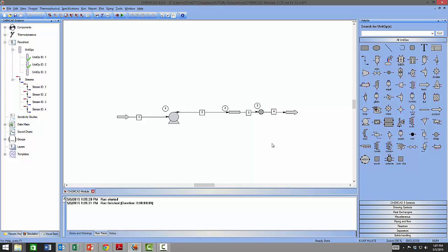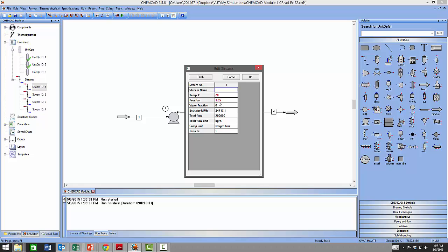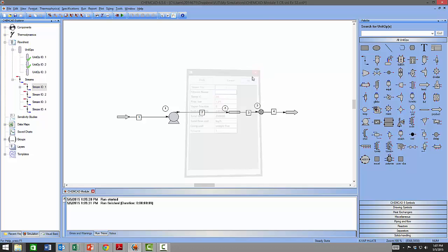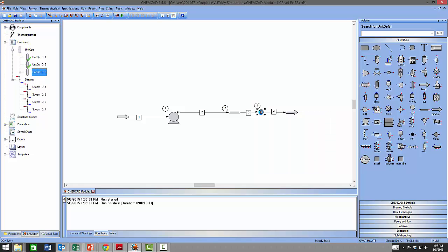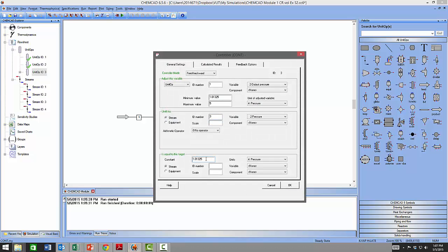I have just realized that I made an error. The stream is coming in at the pressure of 1.05 from the tanker, which is nitrogen blanketed, and then we need to send it through to the storage tank, which has a floating roof, which exerts the pressure of 1.1 bar. So we will need to come and change our targets here in the controller. Our output is supposed to be 1.1 bar, and just to avoid that error, let's just make this one 1.05, which is the pressure of the inlet to the pump.